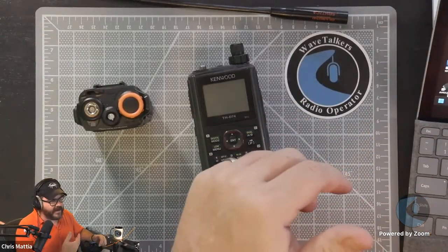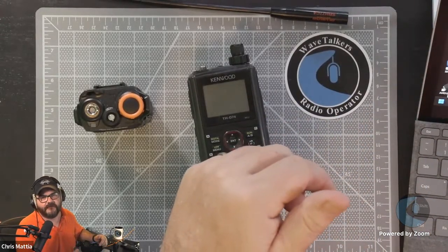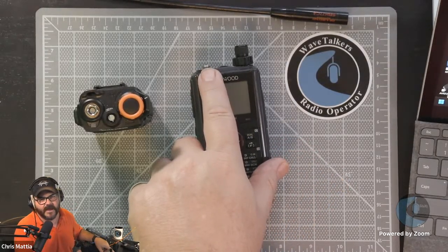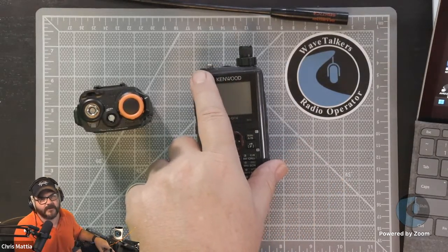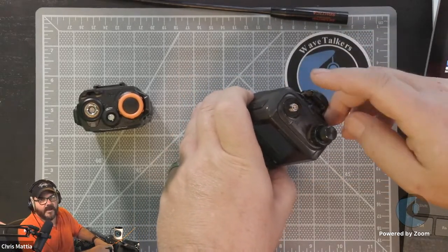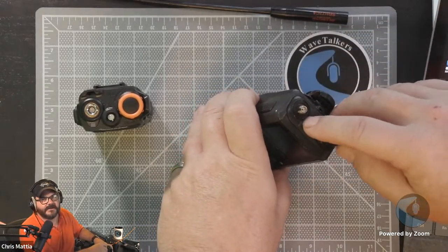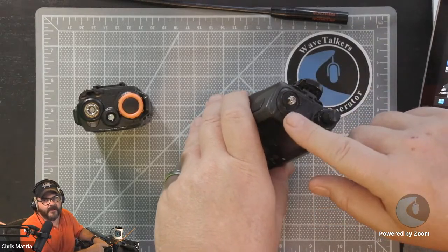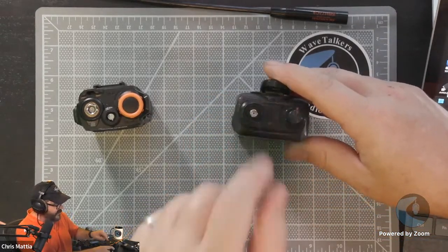When you're doing a lot of changing of the antenna, you're putting a lot more stress on this little small SMA connector. Each time you do that, you're putting stress on the circuit board and the circuit connections inside. These are all pretty well made, but that is a point of failure that you may have. It would be easy to cross-thread them.